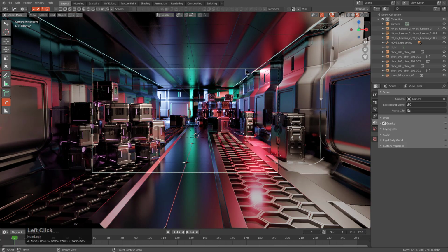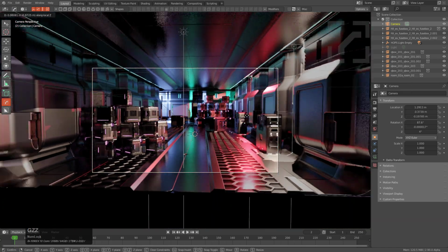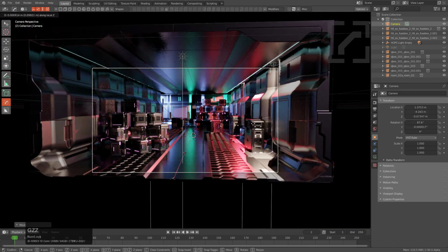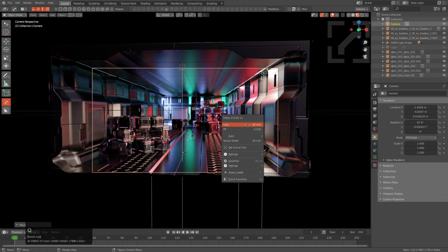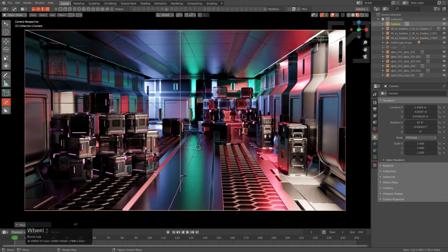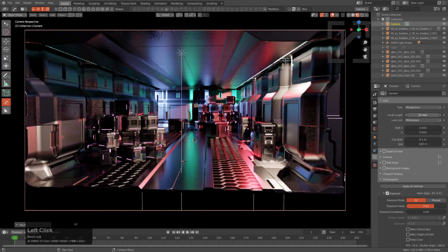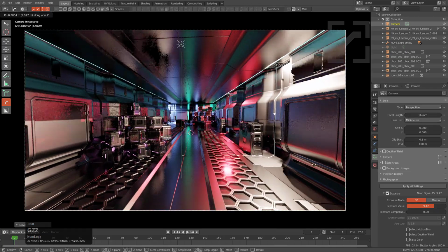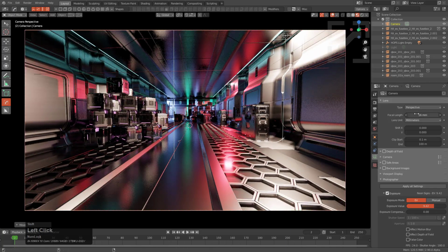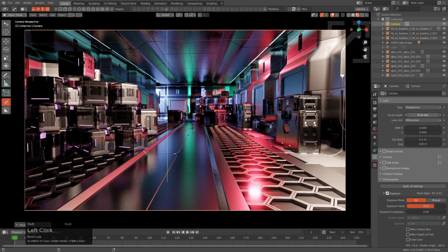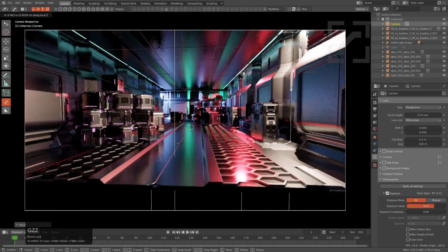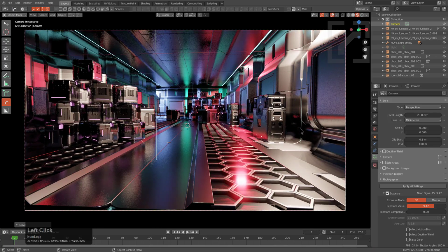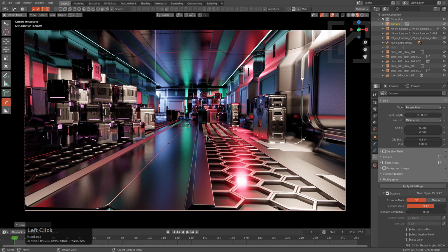And our camera is now enabled, so we'll just select that, press GZ to pull it back, just so we start at the end, raise our PP, and we could probably even play with our lens to get just a longer look down this hall. Maybe not, maybe something more like that. But just like that, we have our lighting set up. And so we could just save our scene if this is where we like it.